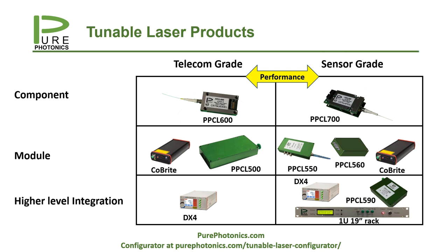They also can all be upgraded up to 16 nanometer tuning range and up to 17 dBm power for C-band and 16 dBm power for L-band. But the difference is in the noise performance at lower frequencies and in the options available for the lasers. Options such as amplitude modulation, frequency modulation, clean measurement, analog output, clean sweep, etc. are not available on the telecom grade product.